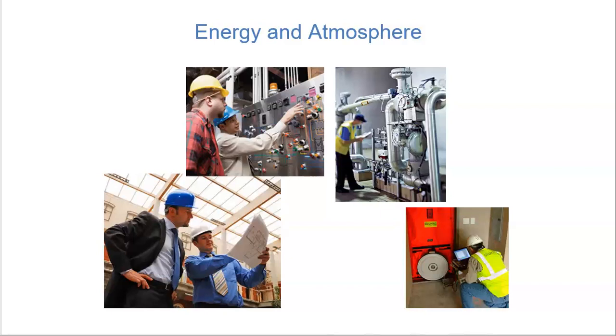The commissioning process activities shall be completed for the following energy-related systems. At minimum, these are HVAC, your heating, ventilating, air conditioning, and refrigeration systems, which include your mechanical and passive controls and associated controls, lighting and daylighting controls, domestic hot water systems, and renewable energy systems, if there are any in your building, such as wind, solar, or geothermal systems.